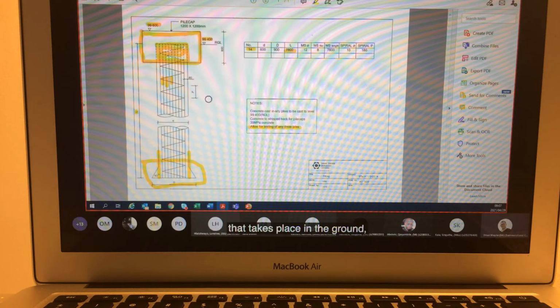With all the movement that takes place in the ground here, you do not want the structure on top to be bonded to that. You want the movement there so that the structure on top can actually move or remain stable when everything below moves. So you'll have a construction joint over there, what you call a shear joint. You guys would know that deal with these.